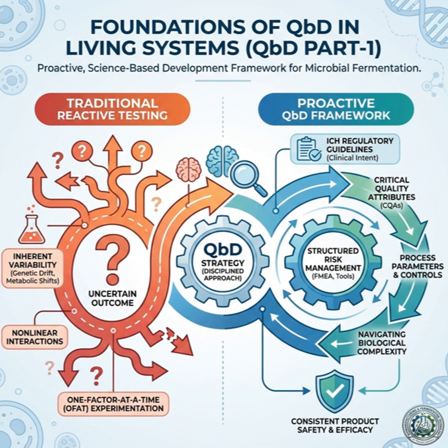And the timing matters. A feed pump failure early in the growth phase has a totally different impact than one during the production phase. A pause early on might just delay things, but later... Later on, that starvation event could trigger that stress response we talked about. Right. Or cause the cells to start eating the product they just made. FMEA forces you to map those specific biological consequences.